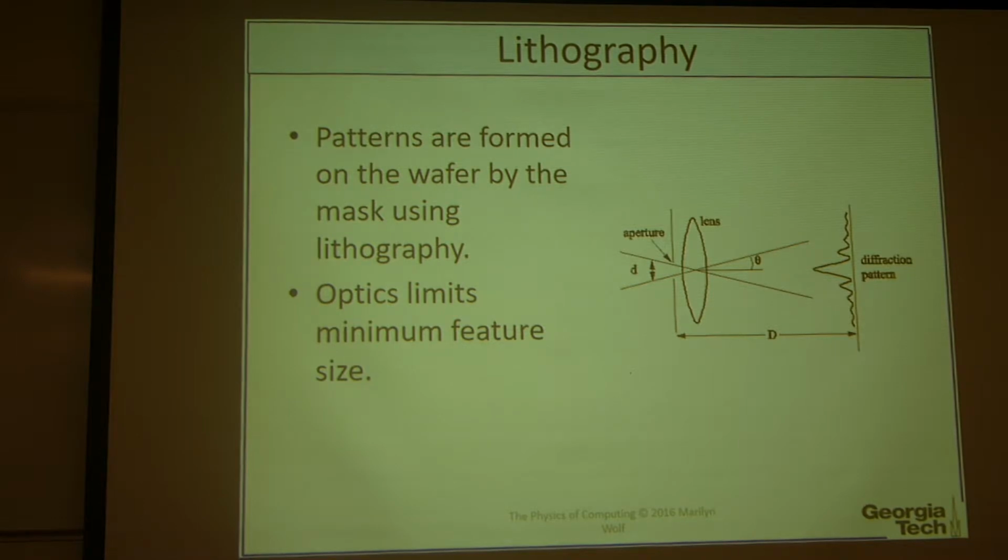And we also didn't go through how this photolithography actually works. So you can see here in the right figure, there is a lens here, and then the light source will be on the left side of it. And then if we emit the light through the lens, there is a sample in the right side, and there is a certain distance of D, capital D here, and then a certain angle, which is theta. So using these values, we can find what resolution we are going to have.